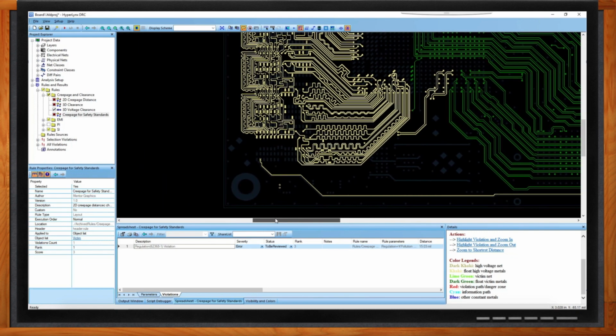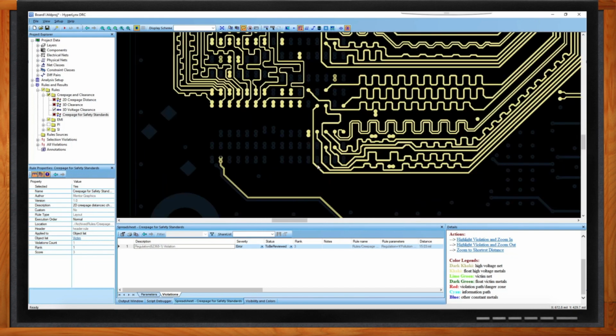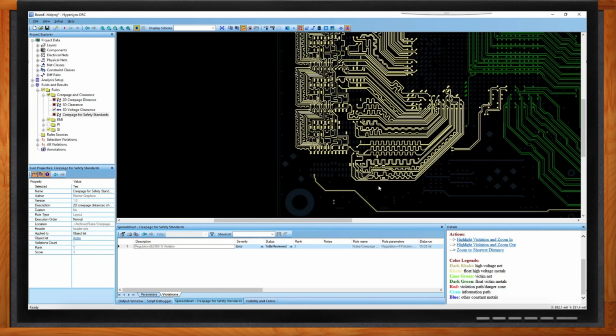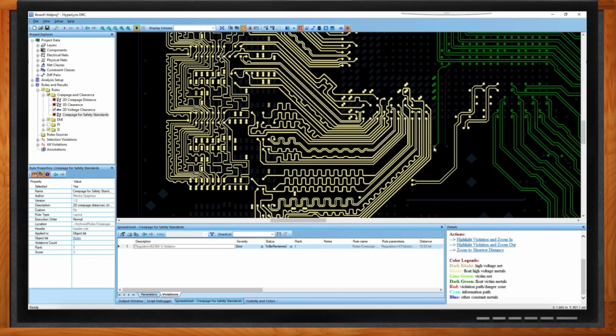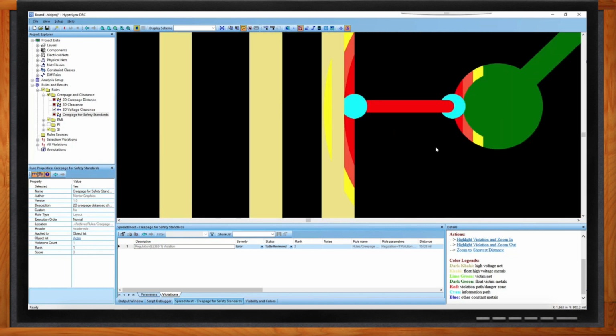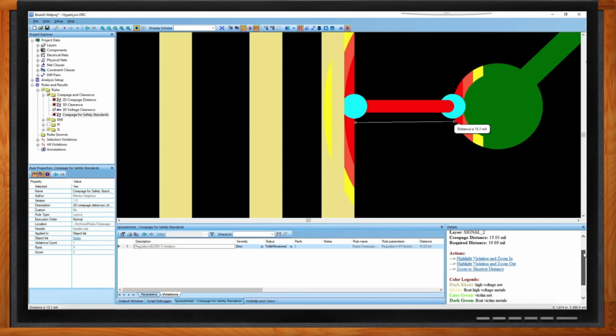In reality, if you move to the left of the board, you see this high voltage aggressor on the bottom is actually creeping to all these other tan nets. And these all can be considered an extension of the high voltage net. So the actual creepage distance between those two nets wasn't 500 mils, it's 15. But to find that manually, you have to go net by net, and you saw how many, we're talking 100 plus nets here on each side.